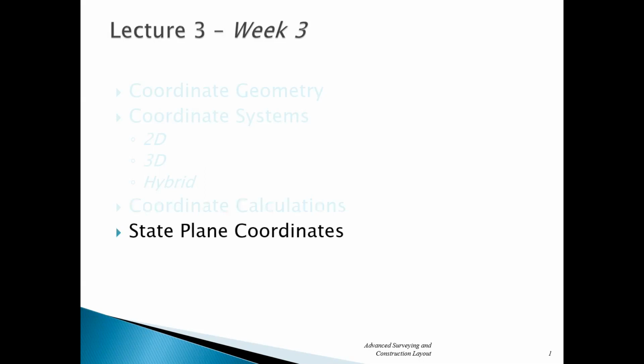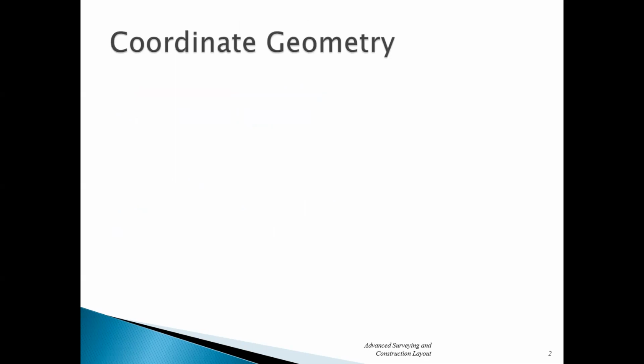And then I'm going to touch on the concept of state plane coordinates. It's not as important for most people, but a lot of people don't understand that this kind of thing is out there, and they'll get sets of plans based in state plane coordinates and then use them just like normal coordinates. That's a big mistake, because that's an incorrect way of doing it. I'll show you how that works, but we're not going to get into it in depth. Any of the surveyors in the class need to understand state plane coordinates a whole lot more, so eventually you'll take a class in control surveying where you talk about state plane in more depth.